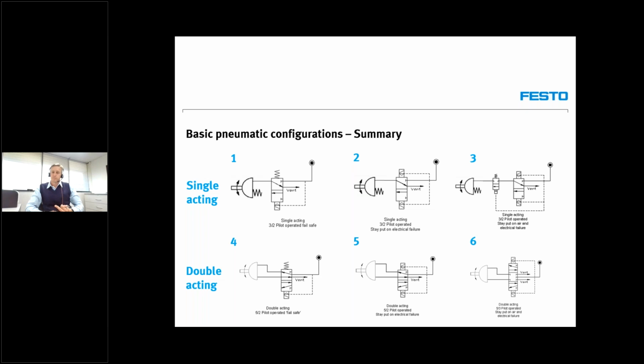Correct. And Horst, what's interesting is there's quite a distinct movement, particularly in the mining industry right now, where there have been some nasty incidents where devices have mechanically failed and caused harm and injury, in fact some even to death, because of the spring packs inside them. So in some places they consider an air vessel as a charger, or call it an air battery, to cause that device to open or close under fail close or fail open conditions, as opposed to a spring pack. Once again, this requires some understanding of how to use different types of valves and configurations to give you the desired result.